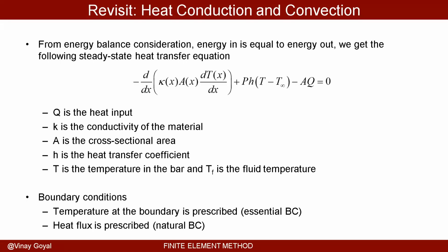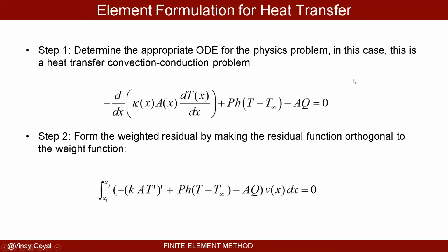So here you have the energy balance consideration. That's the full equation now. We're now including the term for Q, which is internal heat generation. So if you have a component like a wire, you could have heat internally generated from electricity going through, and you'll see that coming up in the project. There you go. That's your differential equation, and the question is how I go about solving it.